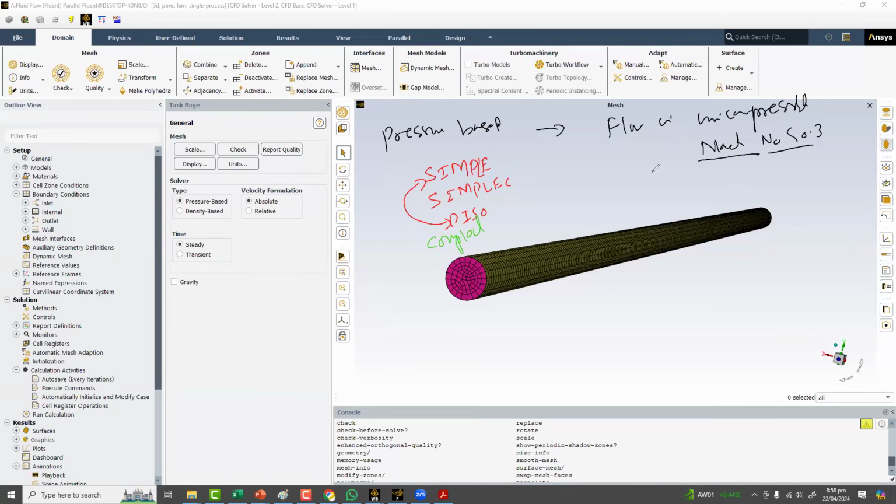So now when you talk about the Navier-Stokes equations, there are actually three kinds of equations. Generally speaking, there are two equations, continuity and momentum, but in full there are more. One is the continuity equation, conservation of mass. Then we have the x momentum, the y momentum, and the z momentum, three components of the momentum equation. Okay, and then we have the energy equation,